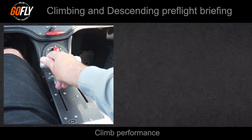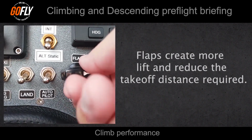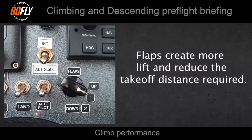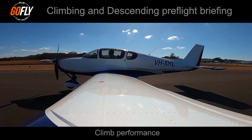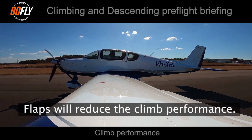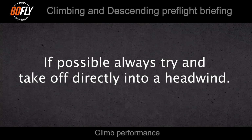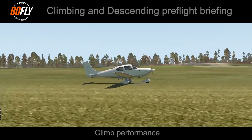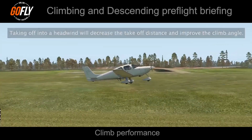Depending on your aircraft type, you may have one stage of flap selected. Flaps are often used for takeoff to create more lift, so less runway is required for the takeoff roll. However, nothing comes for free, and the increase in lift also creates more drag. If some flap is recommended for takeoff, while the takeoff distance is reduced, the climb performance will be reduced due to the extra drag. On takeoff, we always try to take off where possible into the wind. Taking off into a headwind will decrease our takeoff distance and greatly assist our climb angle.